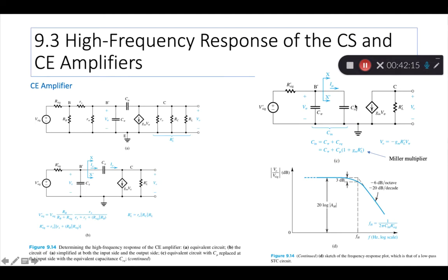These formulas are similar to what we have seen in the MOSFET case, and if you plot the frequency response of the BJT amplifier, you see the familiar shape of a low pass filter. So less than the cutoff frequency of FH, you have almost a flat response. Higher than that FH, your response falls rapidly and is probably not very useful.